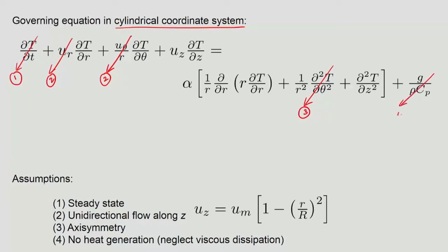So, which means this is the fourth term. Now, we need to have a decision here, and we say that here the ∂T/∂Z is not a function of z, which means that the maximum way by which temperature is varying along the length is only first order slope. So, we would like to drop this off. Okay. So, which means that we can actually simplify the solution a bit.